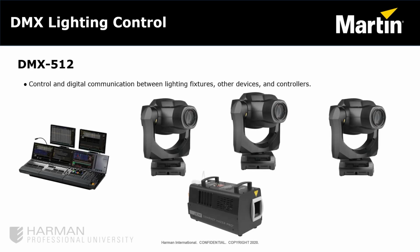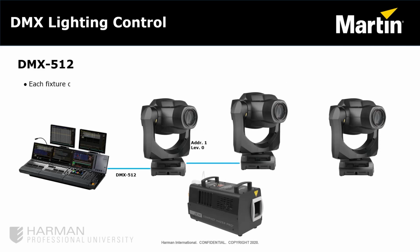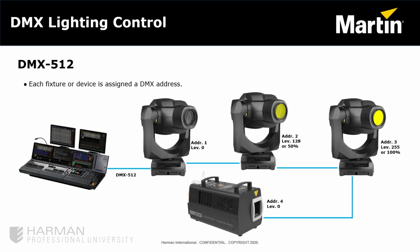Many light fixtures and other devices are capable of having their effects level of intensity adjusted. That level may range from 0 to 100%, where digitally, 0 is equivalent to off or no output, and 100 equals full output or on at the highest intensity. When communication is established between a lighting console and the fixtures or devices, numerical packets can be sent to each product via the data cable links by assigning an address, as well as a value for the level to accomplish a desired output effect. The fixture or device responds to an assigned address and knows to act on the level associated with that address. These numerical packets or values make up the DMX protocol.